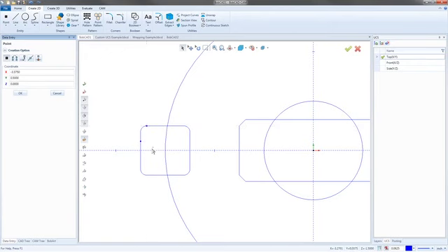I've had a lot of guys call in, and I've talked to them about this in my trainings, as well as a few of the tech guys, who said this is becoming a bigger thing: when you're trying to sketch these points, there isn't really a function to tell it exactly where to go. There is no function for arc center anymore, which is kind of weird. There is, and I'll show it to you in a minute, but normally you'd have a button that says I want to find the center of an arc, and that's what it's going to give me. Now the way you find it is you just hover over the arc, click on the center point, and you're done. It does make it a little bit easier, but it's definitely different. So be careful with it.